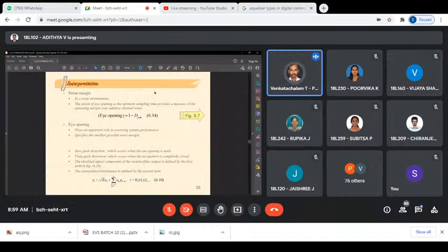So students, you see here, I'm just explaining in the slide. Only when you visualize this in the lab can you try to relate. The eye pattern is between two parallel rails, between the levels +1 and -1. When eye opening is unity, 0 ISI. When the eye is closed, it is closed because of severe ISI. The next one.